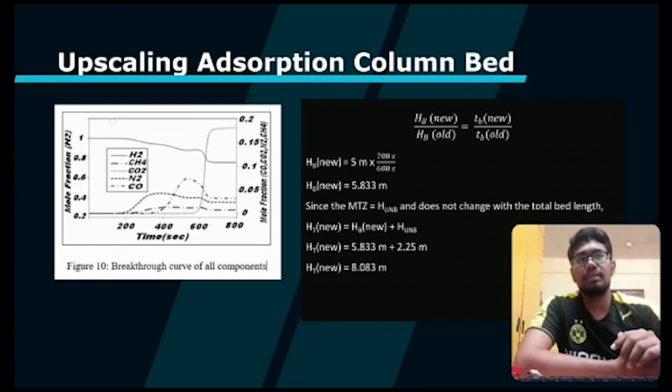Now, scale-up design can be performed. The scale-up principle is that the amount of unused bed length does not change with the total bed length. In case the required time is 700 seconds, the new total height can be calculated, which is 8.083 meter.